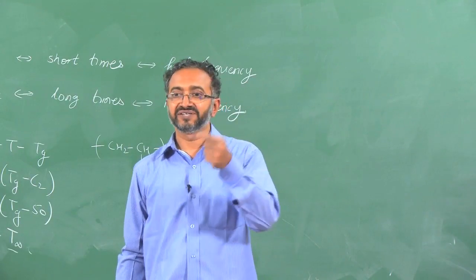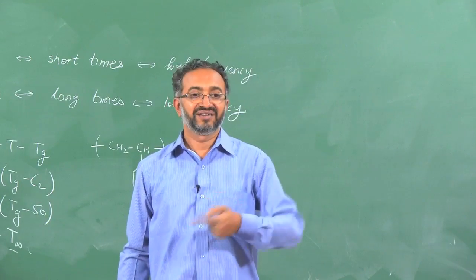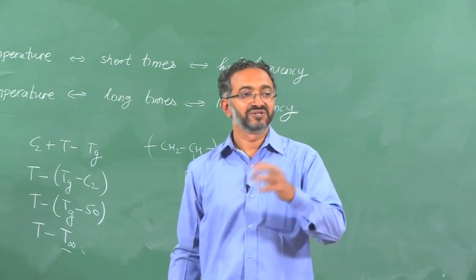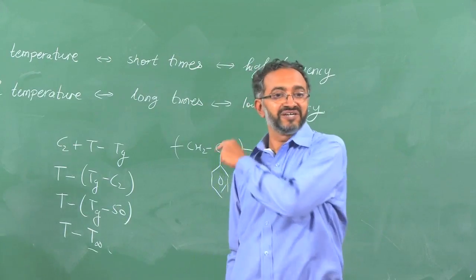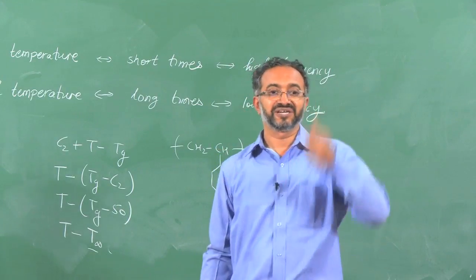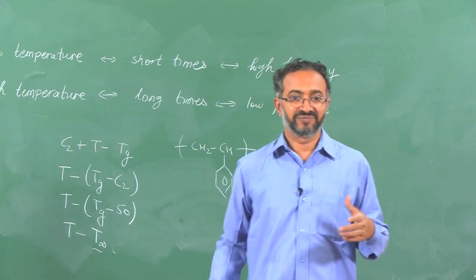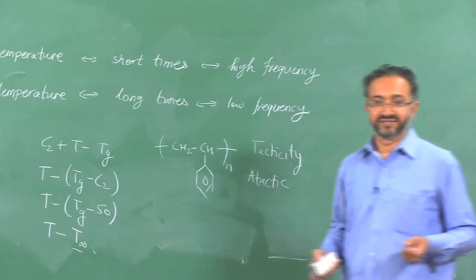I will say that when crystal gets formed, there will be an additional elastic contribution, and I will use a vertical shift to say that the elastic contribution is changing. I can a priori tell you by doing DSC or some other method how this vertical shift will change as a function of temperature. So, you can attempt that, right. Once it is a procedure available to engineers, we can try exploiting it.